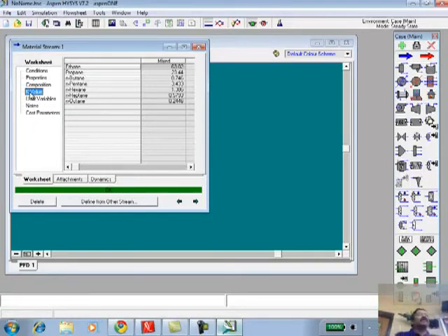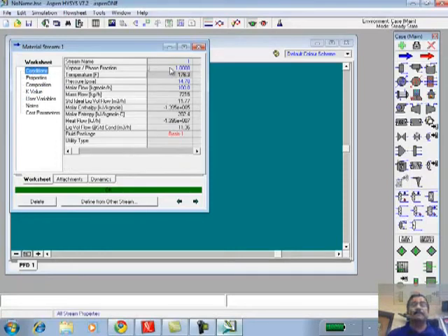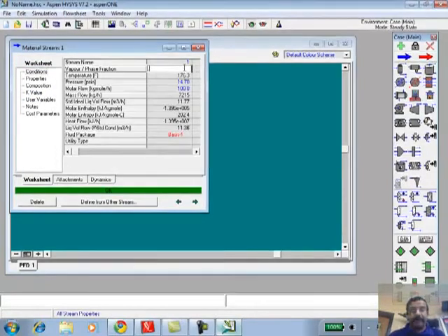When you have a vapor and liquid system in equilibrium, you have something called a chemical potential or a fugacity that is the same in both phases. It is that principle that is used to get the K values, and HYSYS does it for you automatically. And you will see these values change as you change the vapor fraction or the temperature or the pressure of the stream. Any other questions? Let me put it back at 0.5.